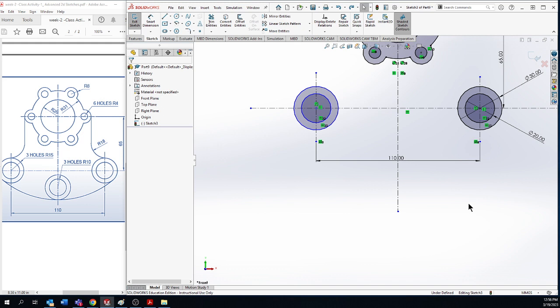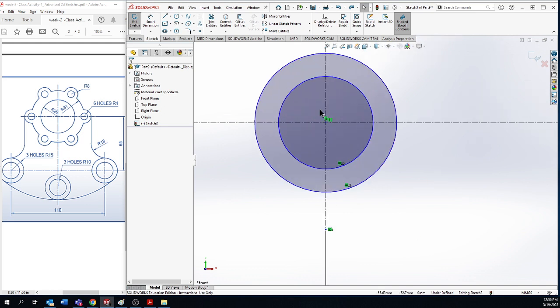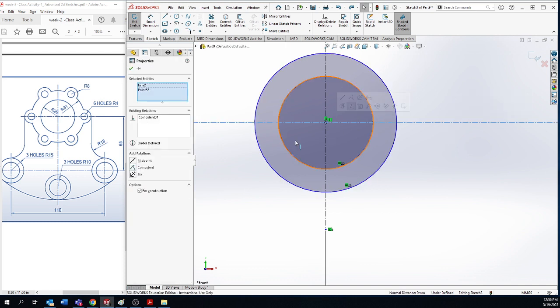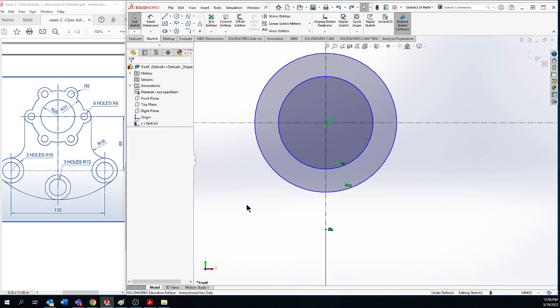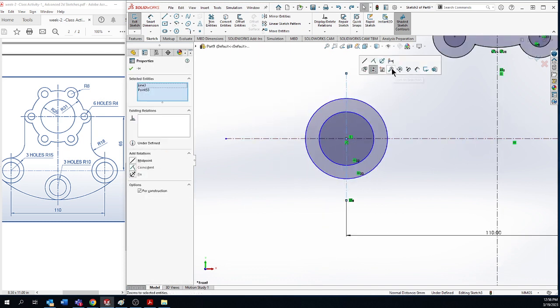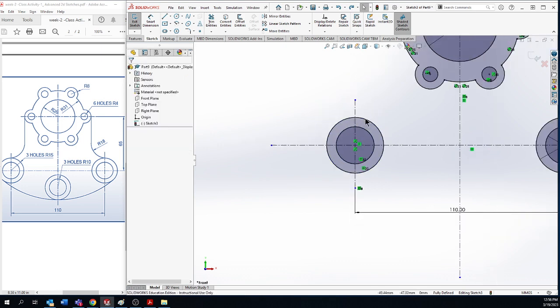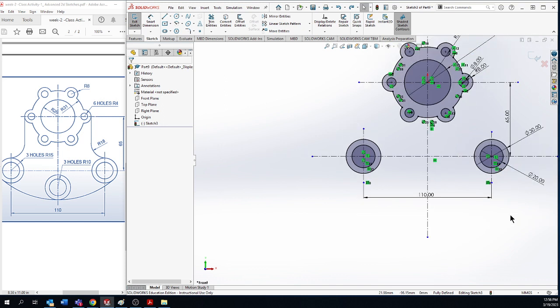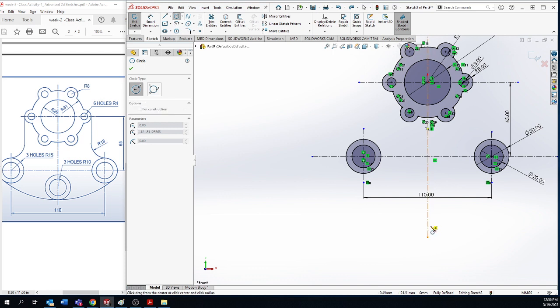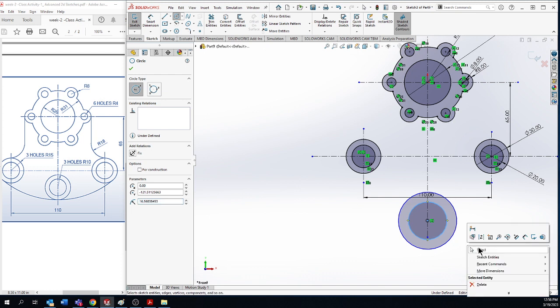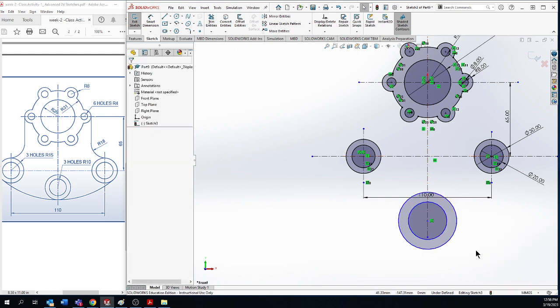and still it is blue color, it must be converted. Let me check. I will introduce this as coincident. Okay, then I will introduce same point with vertical axis, coincident. Yeah, it's done. Just make coincident relationship. So, it comes only by practice. So, you will have to figure out. So, roughly you will be able to draw two circles based on the vertical axis.